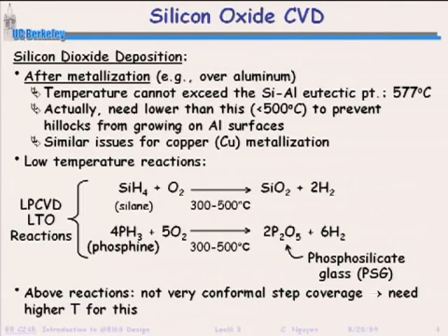For other metals like copper, even though copper has a higher melting temperature, you also need lower temperatures, because in, say, CMOS type circuit applications that use copper, they're usually surrounding these with very low-k dielectrics. And it's the low-k dielectric then that cannot take the high temperature. So even though they've gone to copper for metallization now, the temperature ceilings on the latest CMOS and other transistor processes have gotten even lower because of these dielectrics that they're using around the metals, to reduce capacitance.